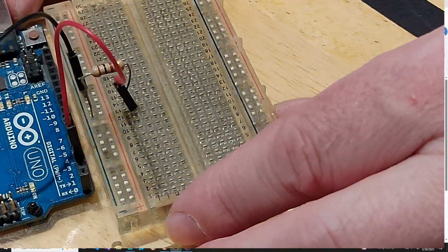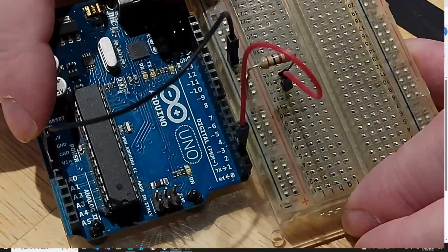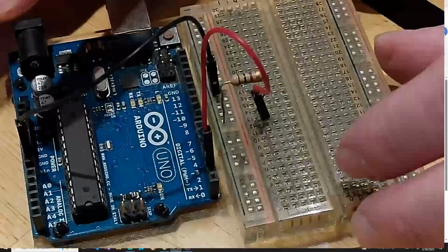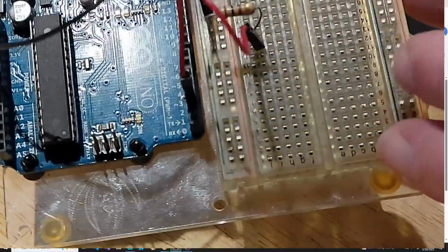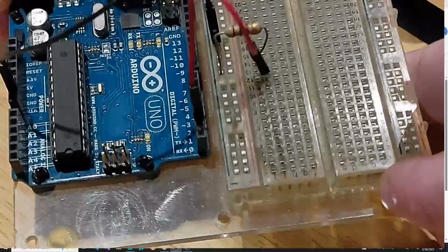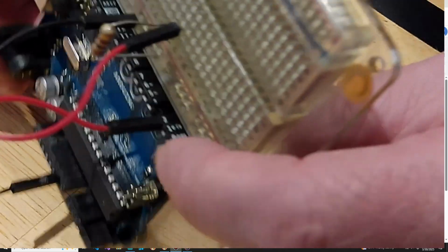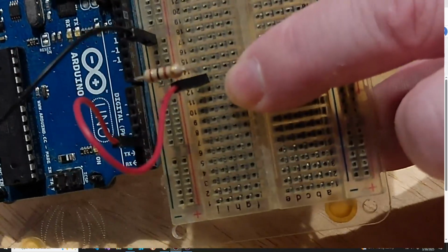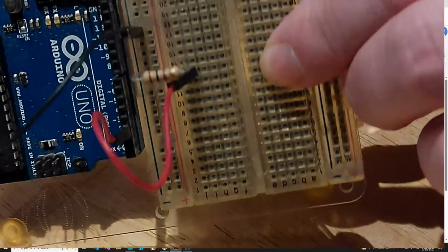Per how Tinkercad is set up, this is exactly how I have it set up. The ground goes into the ground rail, and the resistor is plugged into that ground rail. Then we have the wire plugged into pin number 2, and that's going just right next to that resistor. They're not on the same track. Don't put them on the same track. You're not going to have good results if that happens.